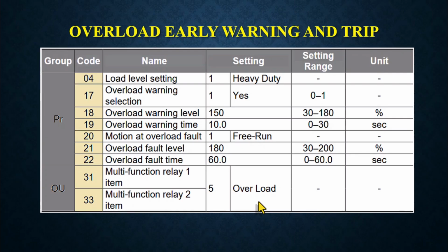All right, so we've now become familiar with the protective parameters that we could set for our electric motor, such as overload warning, overload fault, and excessive heating of our electric motor.